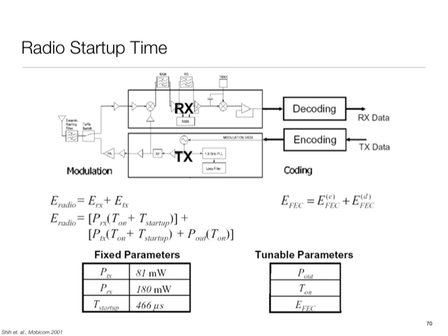For example, for things where electronics is a more significant part. That may happen, for example, for short-range radios, because as I mentioned, in short-range radios, receivers dominate, and receivers are all electronic. So in that kind of regime, your better strategy may be transmit quickly, shut it down. But that means I need to have radios which can wake up quickly.